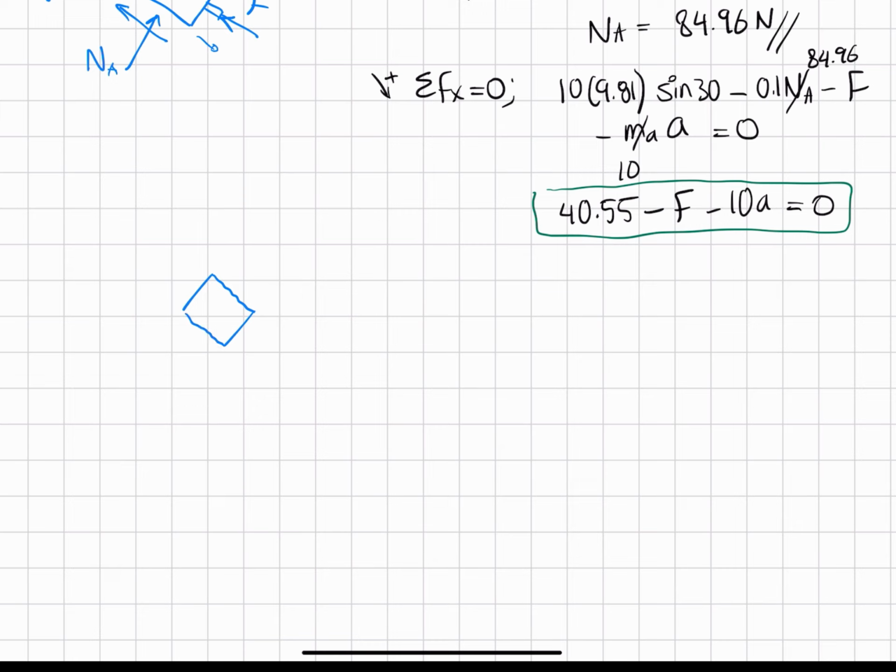The force is going to be acting in equal and opposite directions, right? We're always using Newton's laws. We have the weight, which is 9.81. We have the 30-degree angle and the normal force. We call this NB. If it's sliding downwards, friction will be in this direction. So F of friction is equal to, the coefficient was 0.3 in this example, times NB.